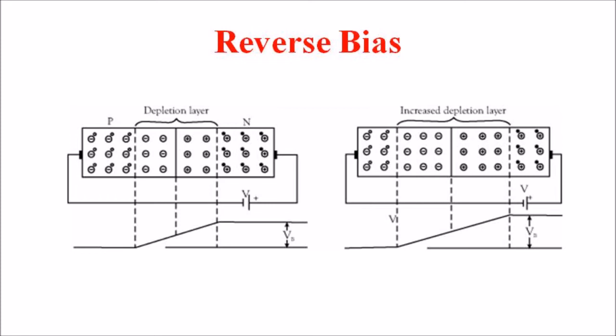Only when the electric field intensity increases beyond a critical level does the p-n junction depletion layer break down and the current begin to flow, usually by either the Zener or avalanche breakdown process. Both of these breakdown processes are non-destructive and are reversible as long as the amount of current flow does not reach the level that causes the semiconductor material to overheat and cause thermal damage. This effect is used to one's advantage in the Zener diode as a regulator for electric circuits.